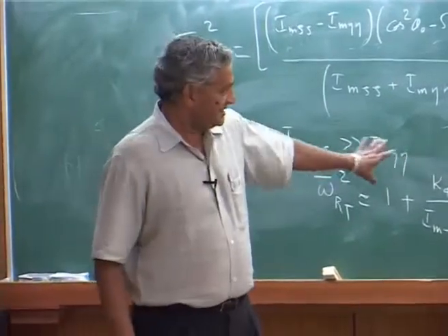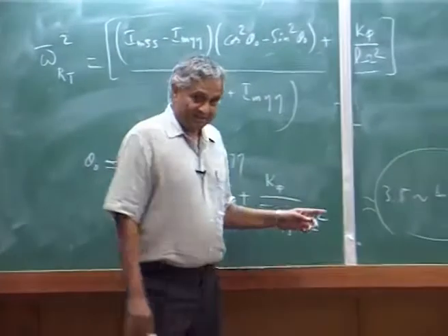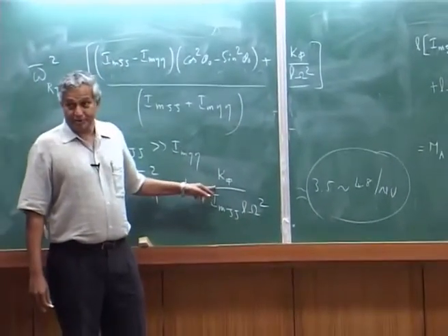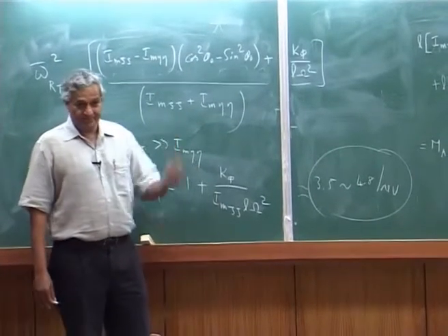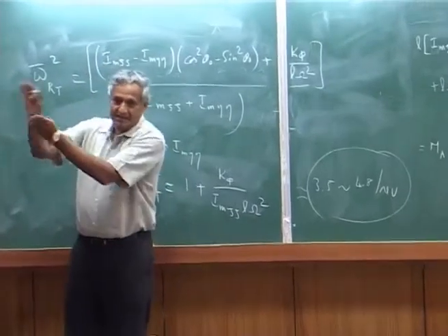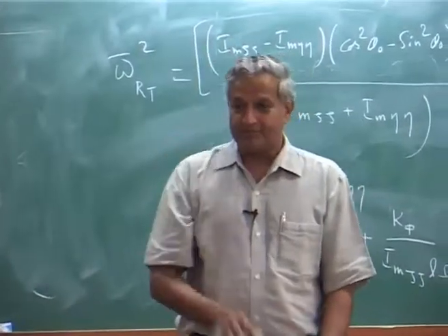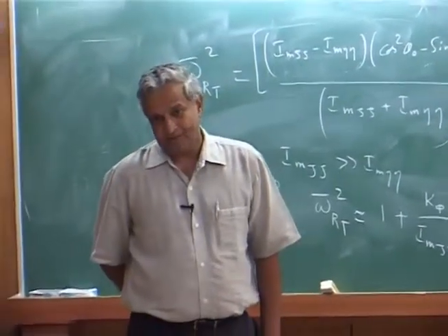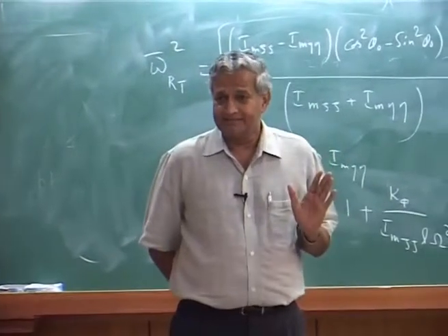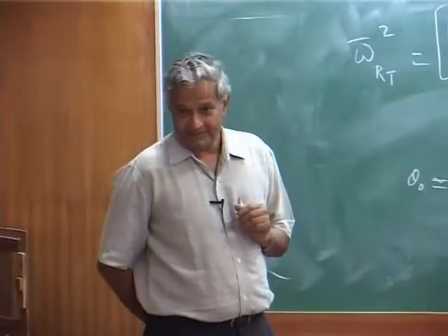Because you don't want to bring this and have a problem. This is mainly dominated to a large extent by the control system. Okay. So if you want to analyze the blade dynamics, you need to know the control system stiffness. So that has to be calculated separately by stress analysis.